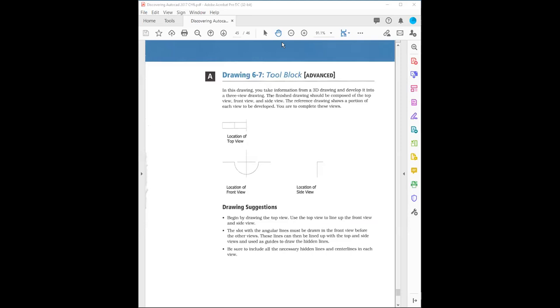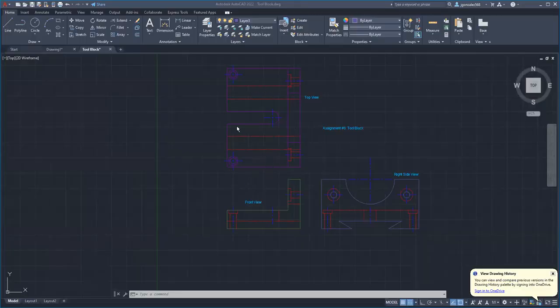I think the one I have is mislabeled, but I think you get what I'm saying. Anyway, this is a rough sketch of what I'm expecting. You look at those 3D measurements and make sure all the measurements translate to a 2D view from different perspectives. Each one is not crazy hard. It's just that you have to pull that information from an isometric drawing. That part is the hard part. Okay. So all these need to match up with this here.